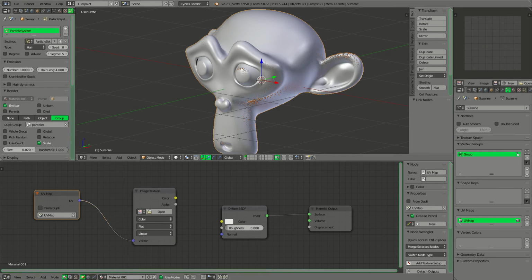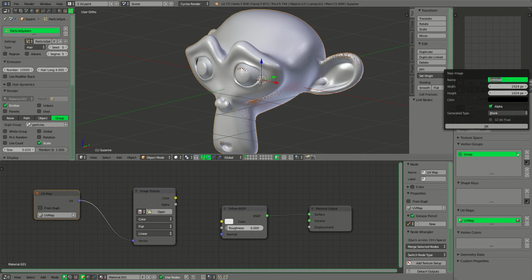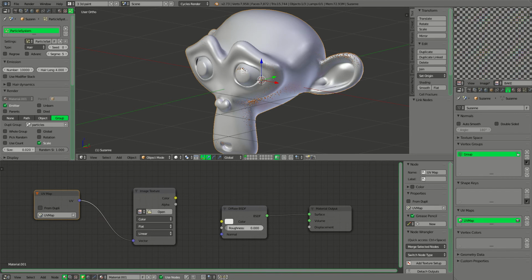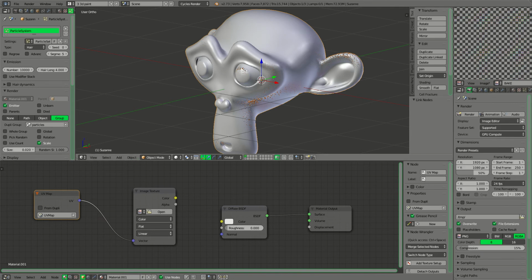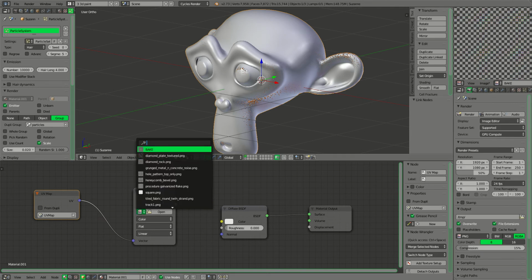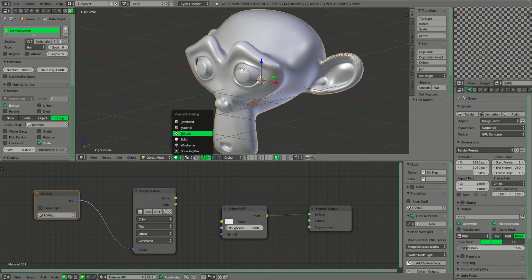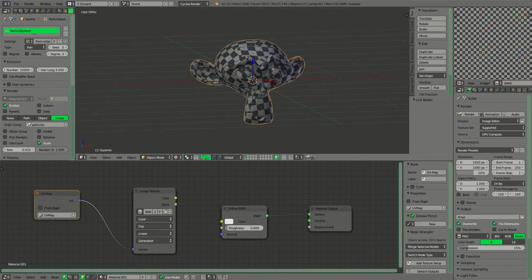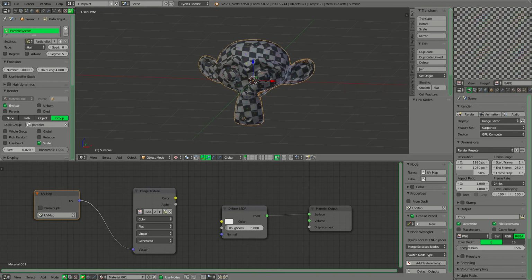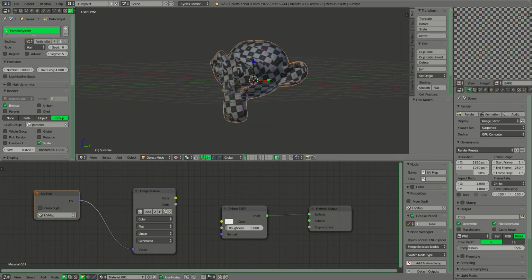We're going to create a new image, and we'll call this stencil, or sorry, bake, and we're going to fill it with a UV grid just so we can see how it works. And we're going to mention there, bake, go to texture view, we can see how it works. So we're ready. We just need to bake this out.